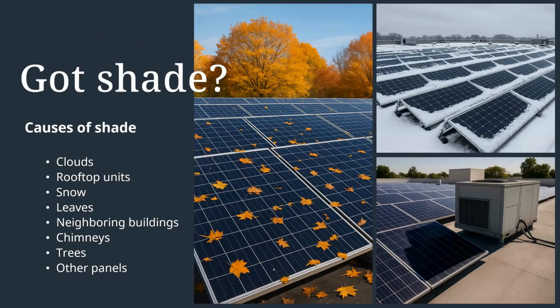One thing that's extremely interesting about Fronius is we've developed and have had in our portfolio for a long time a global maximum power point tracking system. And this works really well when you have shade. So in cases like this, here's a great example, this HVAC equipment is shading the solar panels at certain times of the day. Shade can be caused for a variety of reasons, including chimneys, trees, buildings, etc.